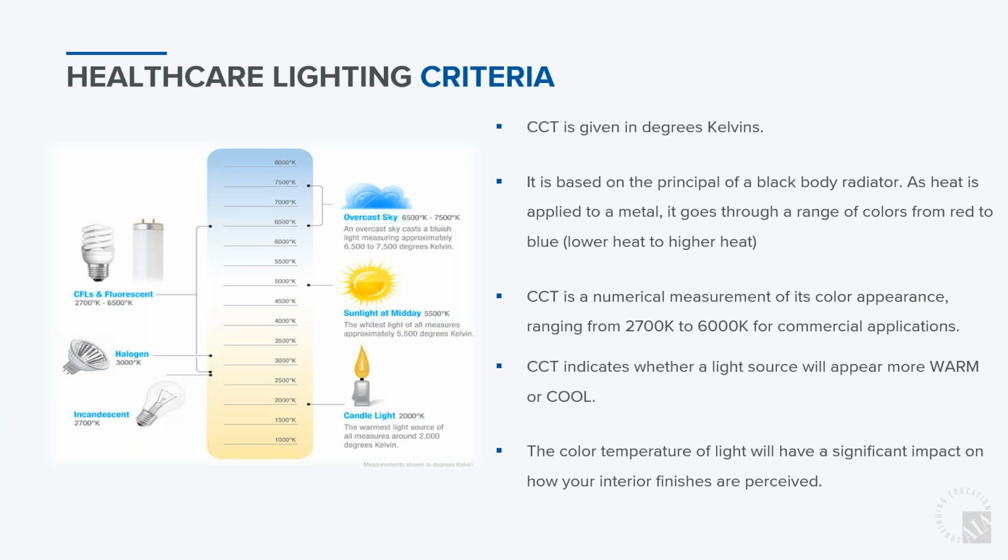So now your ranges are from 2,700 K to 6,000 K, and that's even more so. I mean, there are some ranges out there that are like 1,650 to 9,000. So LED has really opened up a wide breadth of what we can achieve. At the same time, being tunable and controllable, we can set these tunabilities to different daylight ranges, allowing for cleaner, more circadian rhythm entrainment.